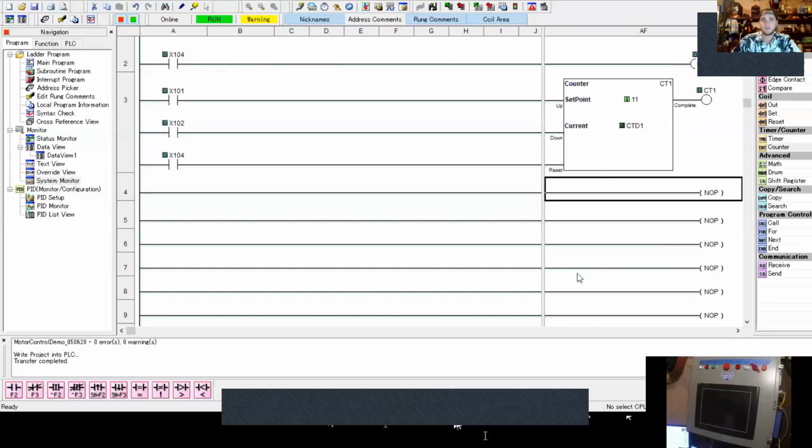Okay. So what that lets us do is we can put in a math bit here. And in this math bit, what a math bit does is it writes some value into a data register. And so we want our data register to be in this result field here, okay? And we could go searching for it in our huge index of things, right? And we can see that DF1 through 8 have been assigned.